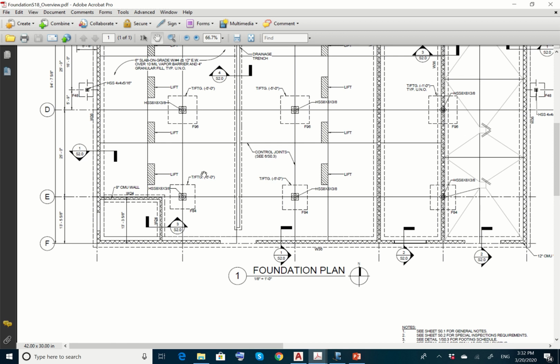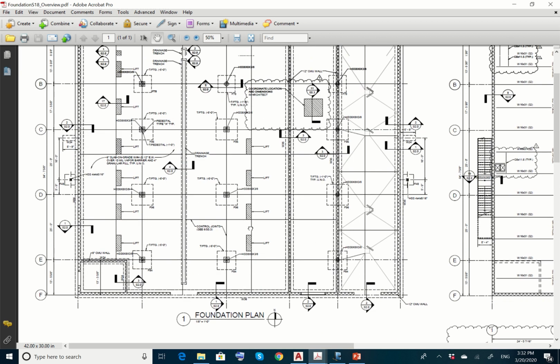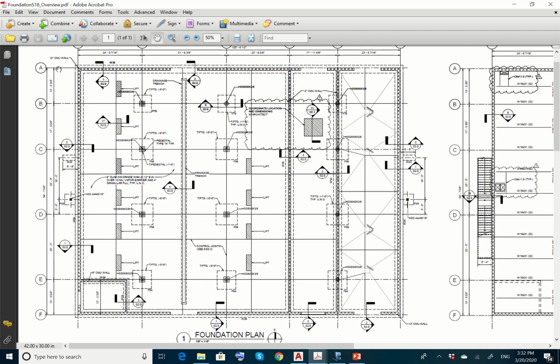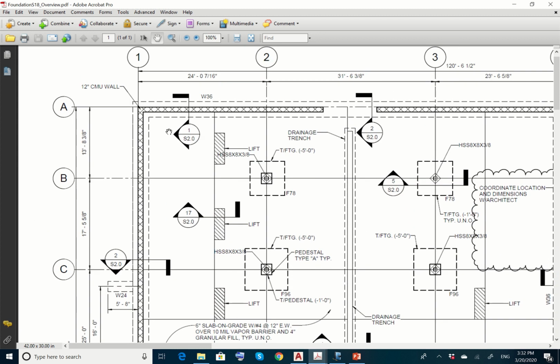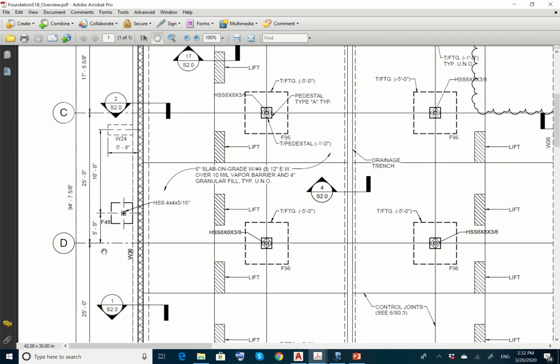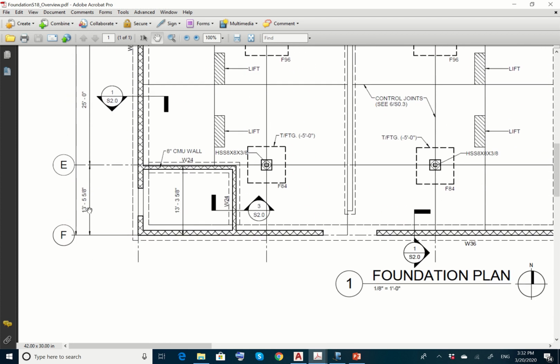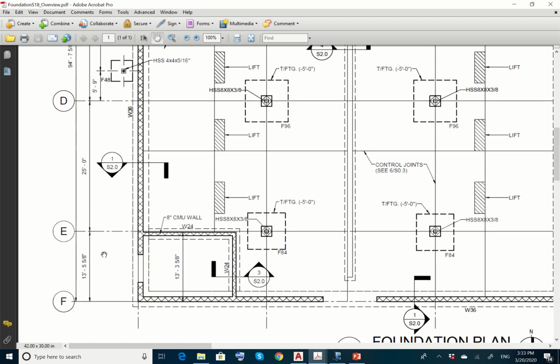Another thing here that you would see, and you're now familiar with this, are those axes, okay? There are those axes and the dimensions. I would recommend that you start by drawing the horizontal and vertical axes. They are labeled A, B, C, D, E, F in the horizontal direction, with the distance between each one of them. You're going to replicate this and fully dimension it exactly as it appears over here.